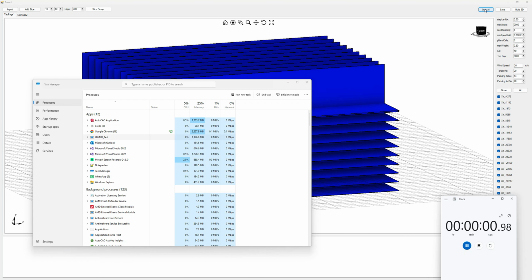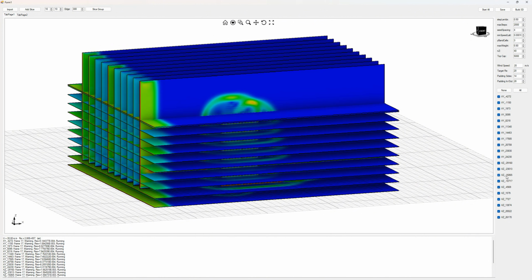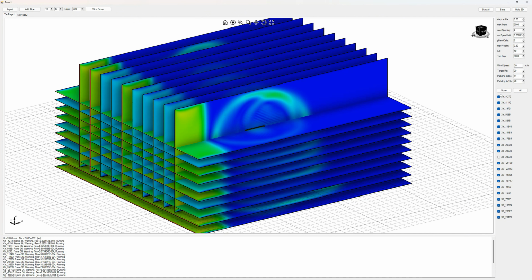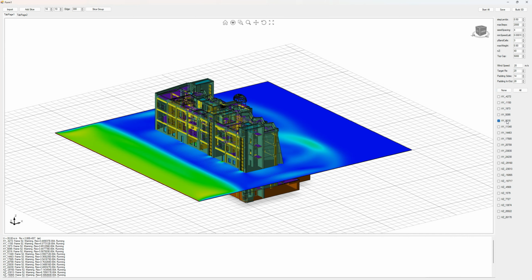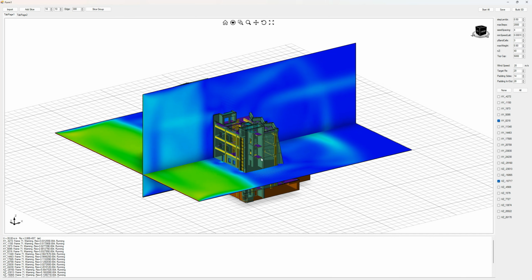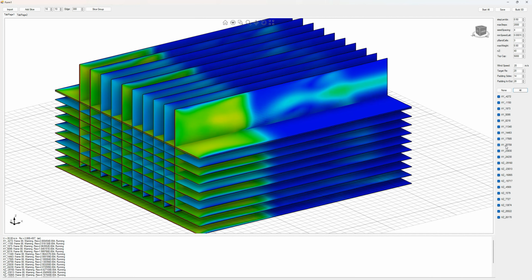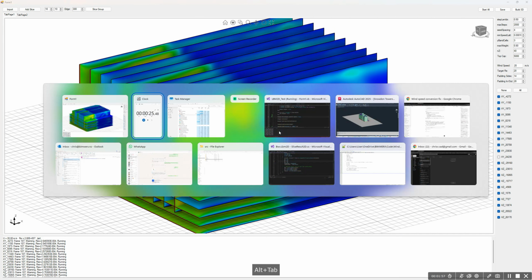And then we'll start our timer, and we're going to start the analysis with all 20 of those slices, 10 in XY, 10 in XZ, and we're going to see how well that performs. Now we can switch slices on and off while it's running, so they're all running on separate threads. Whether they're visible or not doesn't really make a difference. It's the computation in the background for each of those slices on their own threads that matters.